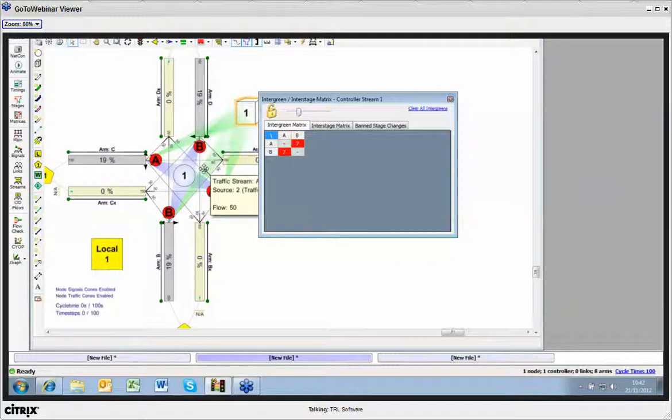I'll also point out, while we're talking about phases, something I probably should have mentioned earlier on. In the UK, we term traffic phases as being a particular movement of traffic. We term a traffic stage as being a collection of phases that run together in one period of time. I appreciate, again, in other parts of the world, we have different terminology for that. Certainly in the case of Australia, they use phase and signal group. They use phase where we would use stage, to denote a selection of movements running together, and they use signal group where we would use phase.